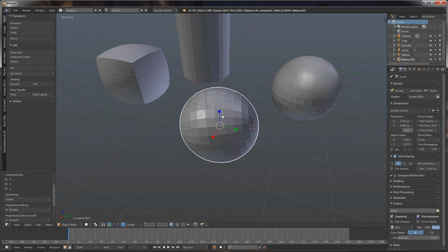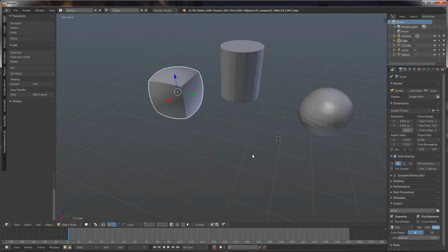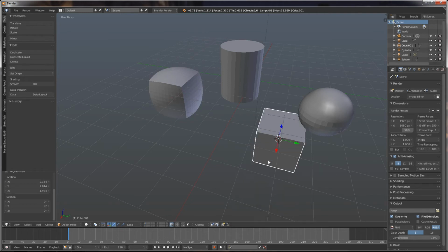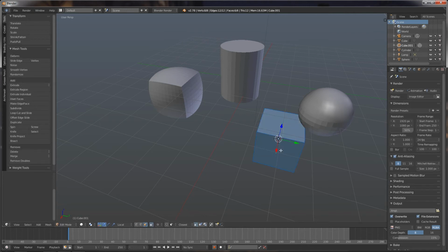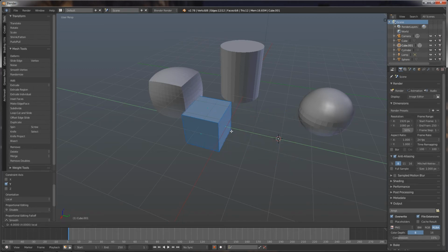An easy option in order to move objects precisely in Blender is to use Snap. First, let's delete the UV sphere. Add a cube to the scene using Shift A. Then tab into Edit Mode. The easiest way to snap objects is snap to grid. Choose the snap object and move the cube using the Translate manipulator. Notice that the cube snaps to the grid.